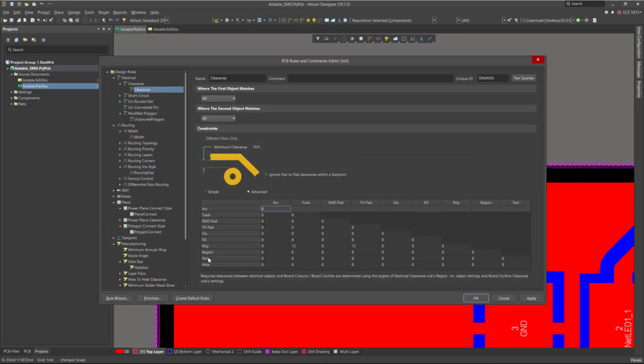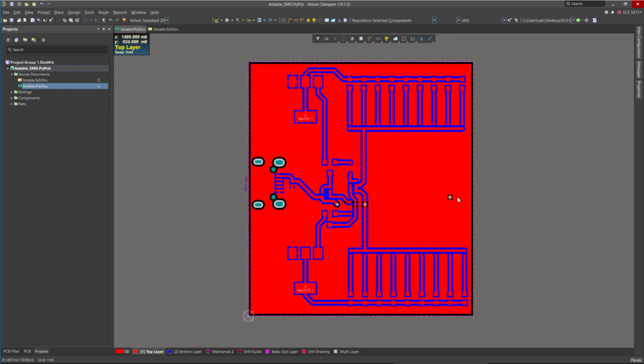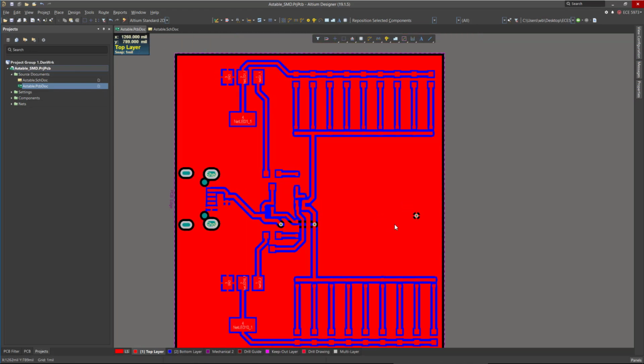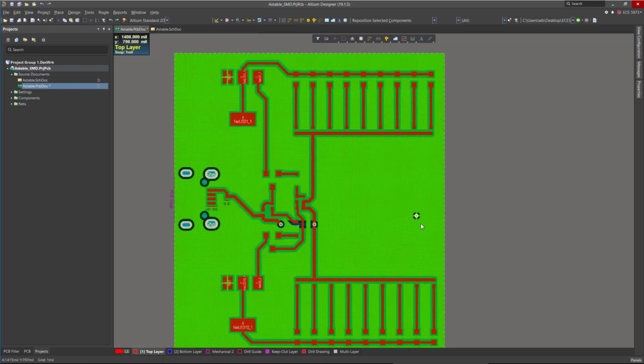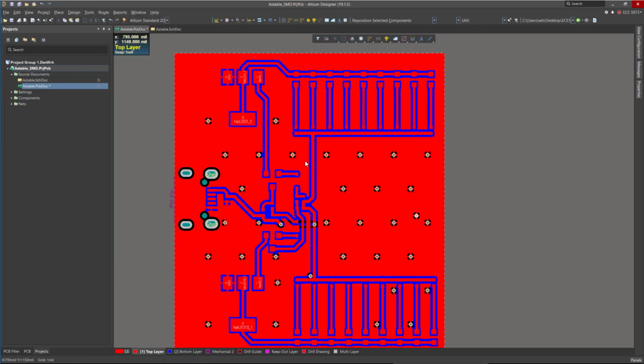So if you go back, you have a poly, and you have trace at 12 mil. If you have anything else, these are the distances between the polygon and anything, a trace or via. This will be considered as trace. And for some reason, okay, Tools, Polygon Board, Rebuild All.